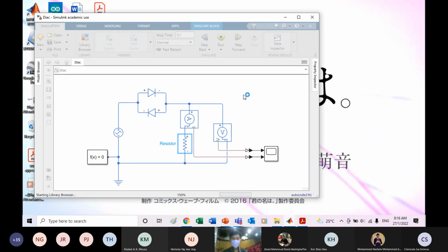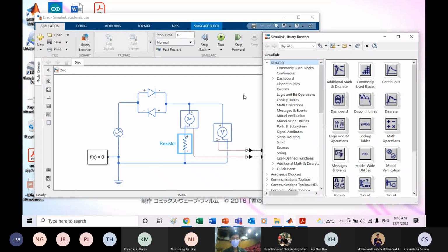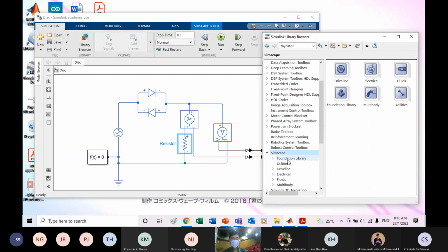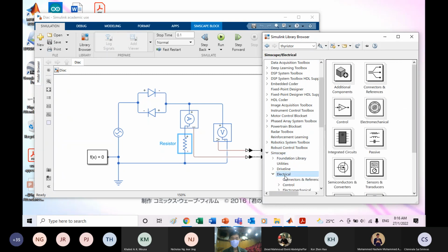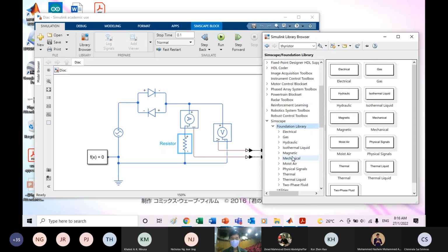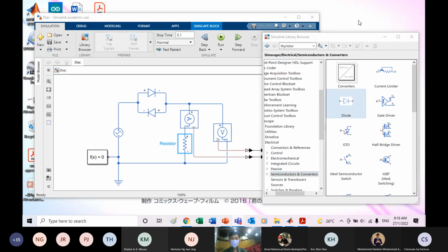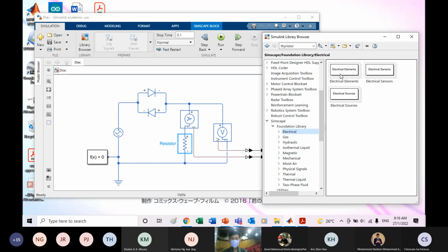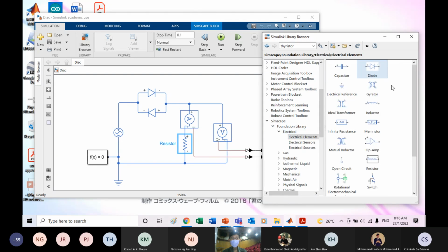Like I said, this diode, in fact, the detail diode also can use. So you don't do much changes except the forward voltage. And you can find it in the Simscape. It's the same lah. Or you want to look under semiconductor, so the diode here, or electrical. I think we have another. This is a simple diode, okay? You can use this one.